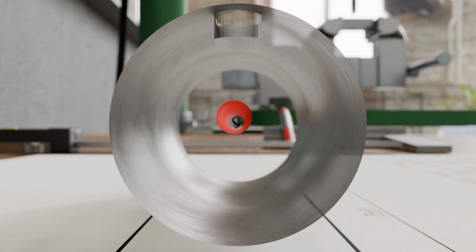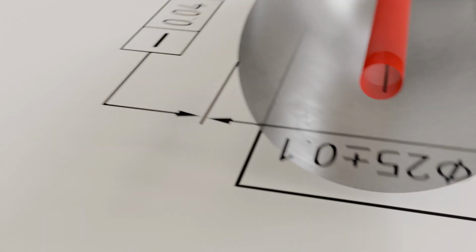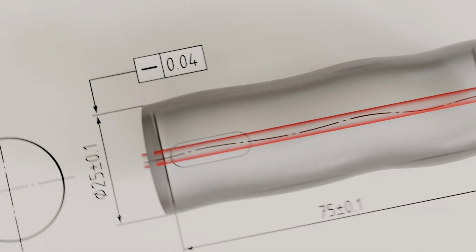It should also be noted here that the position of the tolerance cylinder is not specified. The only requirement for straightness is that the shaft axis must lie within the form cylinder, but the tolerance cylinder itself does not have to be aligned with the cylinder. In particular, the tolerance cylinder does not need to run exactly coaxial to the centerline of the ideal shaft. It can also be offset or slightly inclined relative to the centerline. The only condition is that the actual shaft axis must lie within the arbitrarily positioned tolerance cylinder.